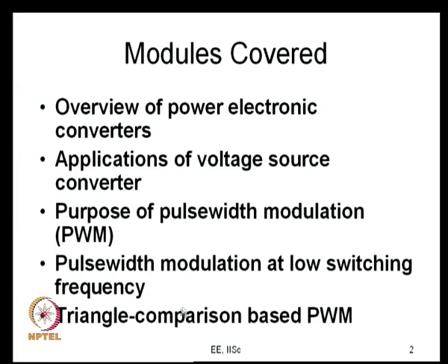That happens in high speed drives, and in such cases the ratio of switching frequency to fundamental frequency is low, and once again this becomes relevant. And what I would say is, rather than the relevance of this to the present context, this has more value to us from a learning point of view. It is a very useful step to go through this, to learn how to control fundamental voltage and how to handle the harmonics, which are the two objectives of pulse width modulation. The low switching frequency gives us a very good opportunity to learn that, and that is the reason why we went through that.